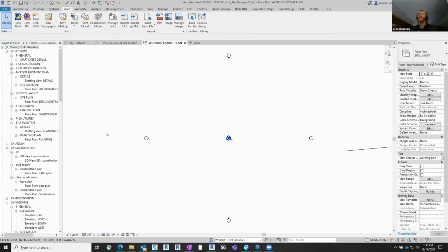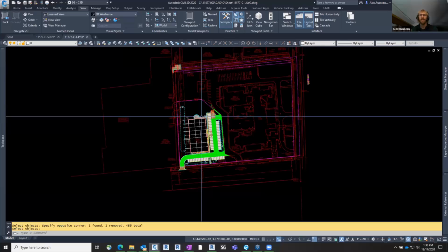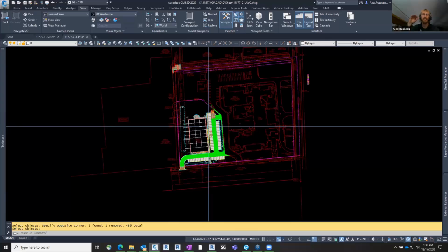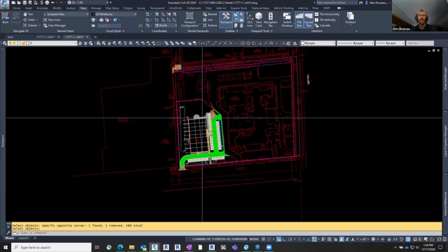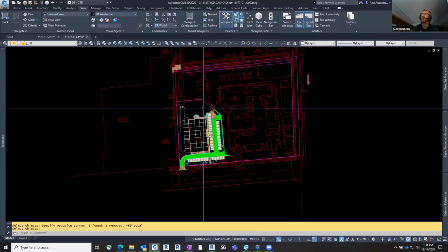Okay. Yeah, that's honestly what typically happens with a CAD file: oftentimes the line work is all drawn at 0 elevation, but the surface elements such as contours hover up high. As long as the surface style is set up in Civil 3D to show your contours, when you export that, the contours will still be shown. They're just going to be polylines at that point, so they'll have an elevation associated with them. When you bring it into Revit, they'll have the true elevation, whereas all the line work would be down at elevation 0.